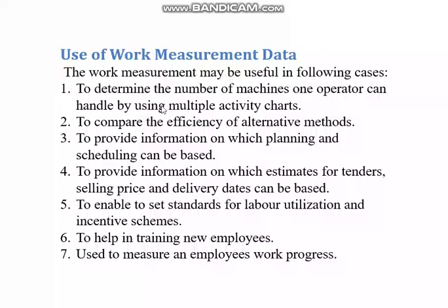Thereby you will be able to determine the number of machines one operator can perform. If the worker says, no, I have one machine only, I will operate, you can clearly tell him, no, for handling this machine you require this much time, and this machine this much time, both you can operate. Okay, that's the first point.